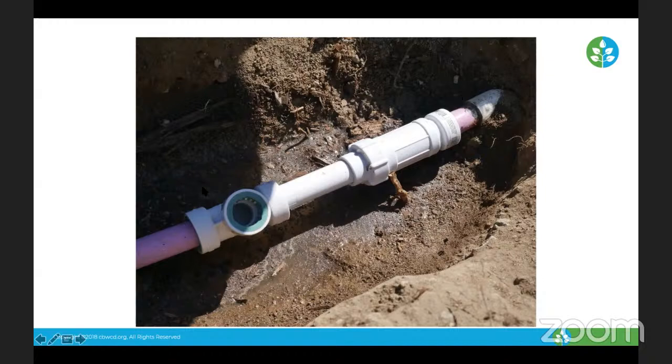This is definitely less invasive, because you can cut the pipes, put the slip fix in completely compressed, glue it, and then extend it to cover that space without having to bend the pipe and do some other wizardry on moving the pipe to get the glue on the fitting.